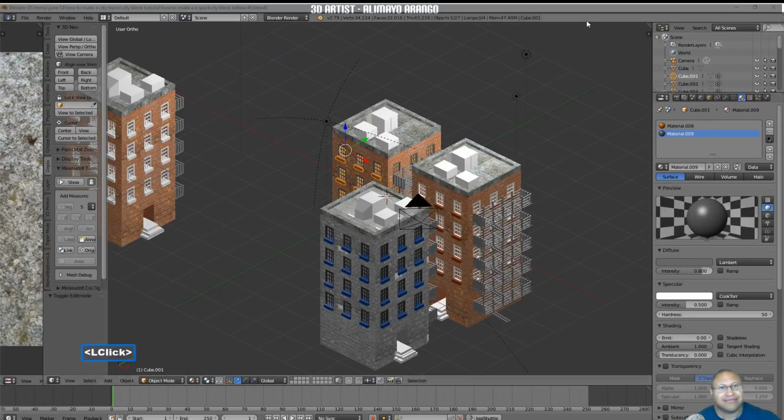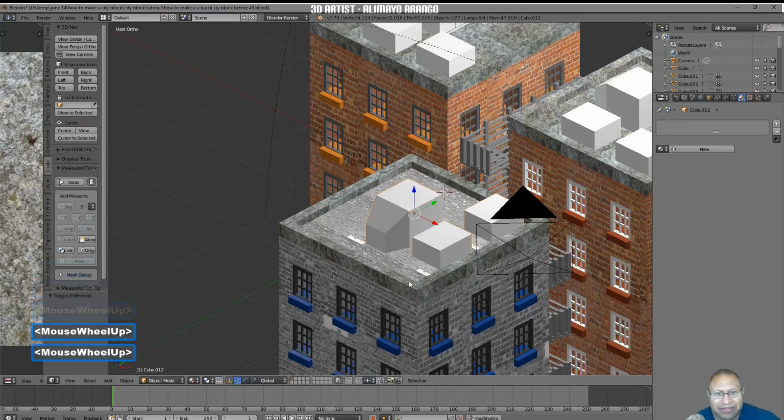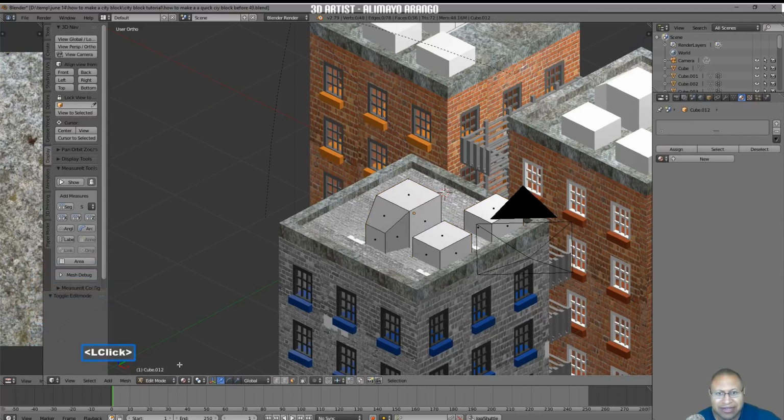Okay, when you look here, you can see how sharp this is. So what we can do is, with those clicked on, we'll go to edit mode. We'll press A to select all of them. We'll hold Control, press B, hold Shift for a smooth select. I'm beveling the edges. So now I'm going to left click, and I have this edge here. So now I look to my left where I have my bevel options. I'm going to take this segments up to 4.